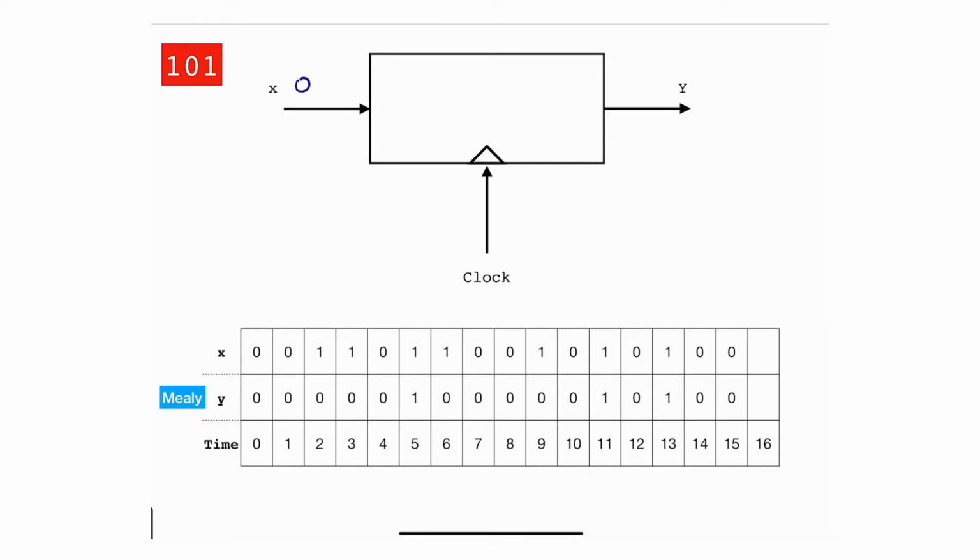Then the next one in here, you're going to see that I'm sending another 0. This 0 here was read by the finite state machine, and my finite state machine will see and remember that it saw a 0. So the next one here is this 0 now. And again, it will go in here, and you can see this is at the next active edge of the clock, and you'll see that the output is still 0. And it goes on and on.